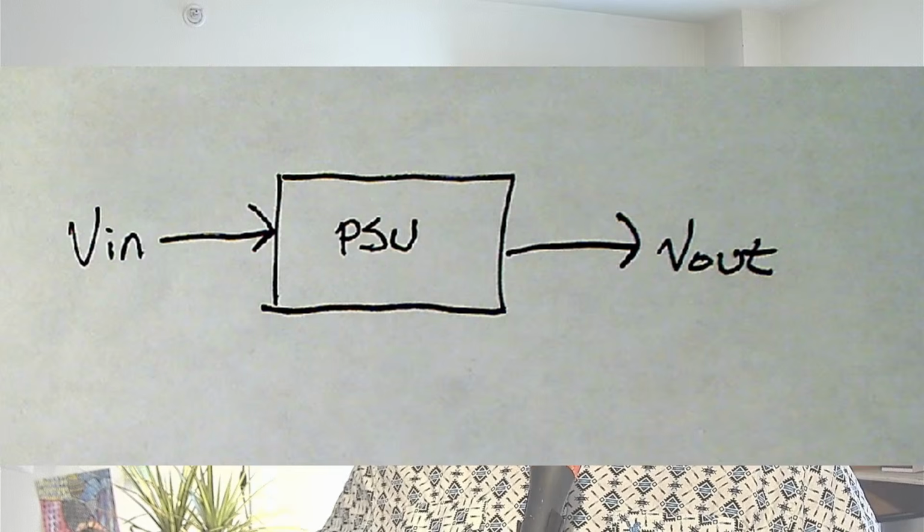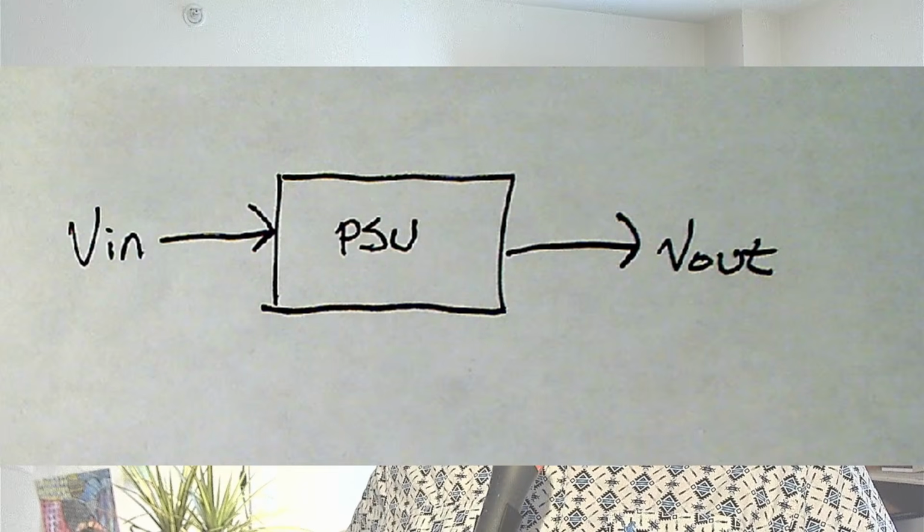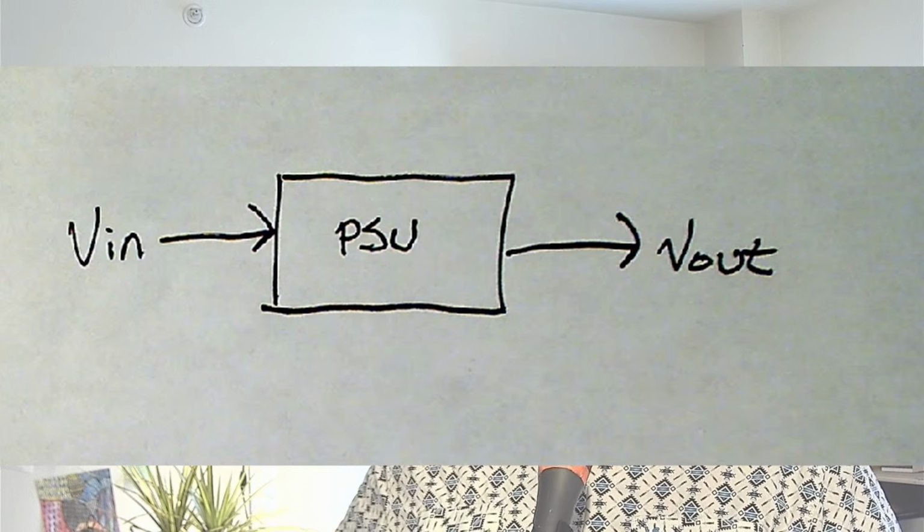Now, just about everything I design is going to be a power converter. That's my specialty, power converters. So, how does analog circuitry show up in a power converter? Well, a big way that it shows up is in the sensing circuits. You know, a power converter has an analog input, an analog output. You need to know what is the voltage on the input. Maybe you need to know what's the voltage on the output.